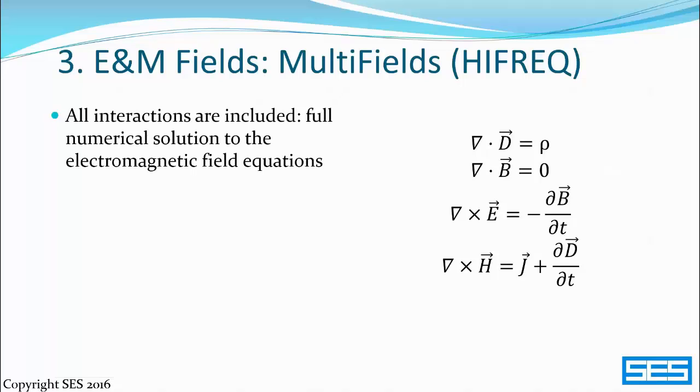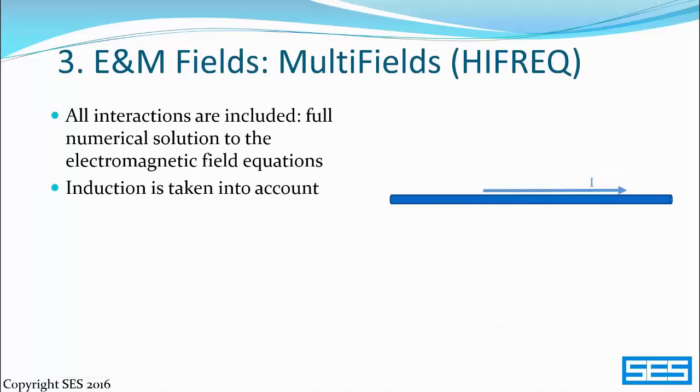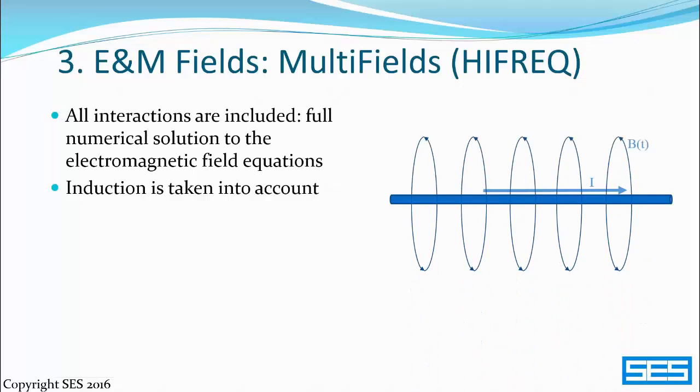And by the way, the high frequency capabilities in MALZ and HIFREQ certainly don't prohibit using them at very low frequencies as well. Solving the electromagnetic equations means that inductive coupling is now taken into account. Of course, so is capacitive coupling, though for fault studies it's less important. Inductive coupling results from a longitudinal AC current causing a time-dependent magnetic field, and conductors nearby will develop an EMF along their length, which is going to impact how current flows along them.